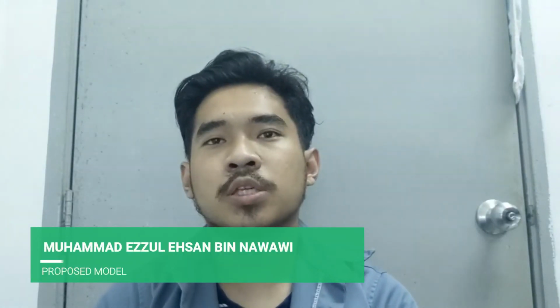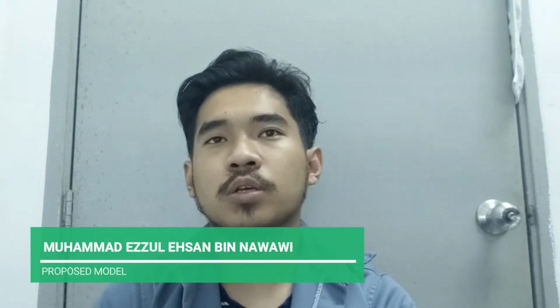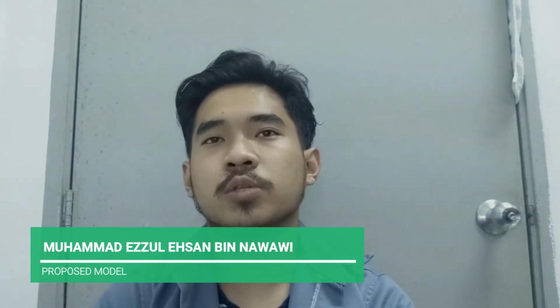The three types of model, which are the soft soil creep model, hardening soil model, and Mohr-Coulomb model, are used to complete this study, and we insert them into the Plaxis 2D software. For the model that is proposed, the model for the 1D consolidation test was based on this figure. The load will be applied at the top of the soil column.